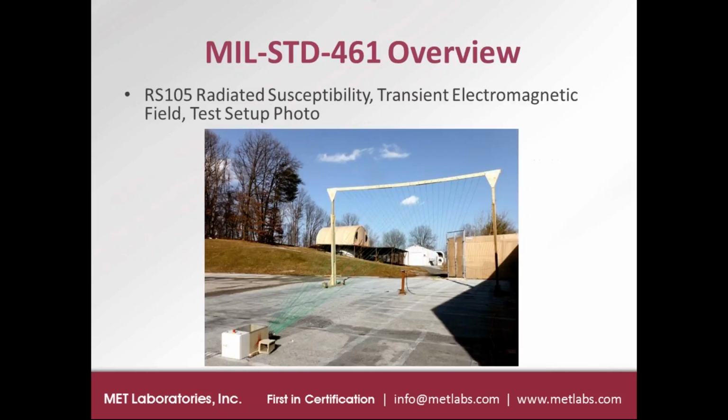This slide shows a test setup of an RS105 electromagnetic pulse test that was done outdoors. The test can be done within an EMC chamber if certain clearances are able to be respected from the top of the septum of the radiating lines. But when you have an EUT that goes beyond a certain height, where the EUT needs to be 1/3 the height of the septum, then the test can be conducted outdoors.